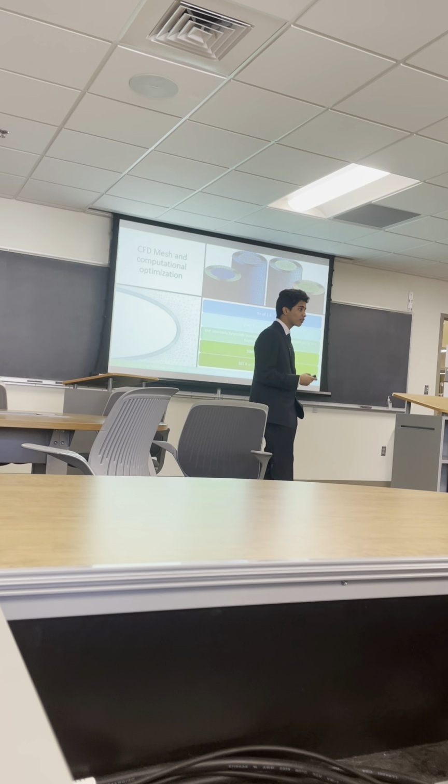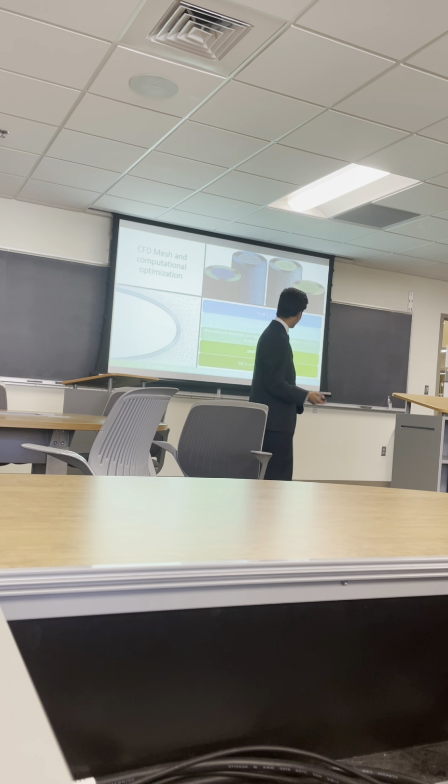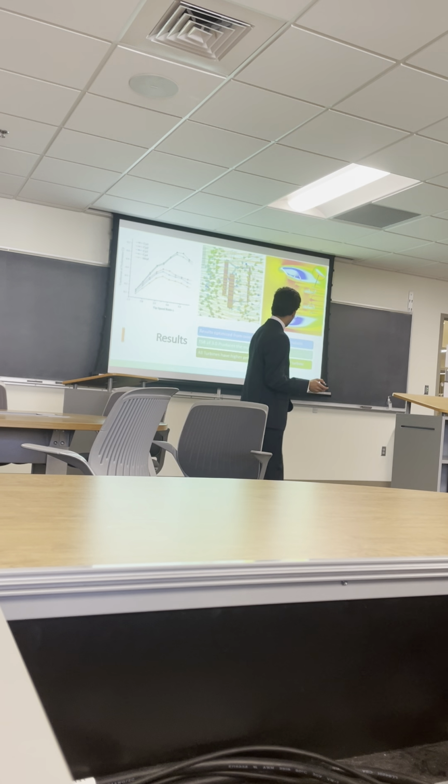For the simulations, the criteria were that y+ should be less than or equal to 1.1 over 3 million elements, and then I used the semi-implicit pressure based equations with the SST k-omega turbulence model.